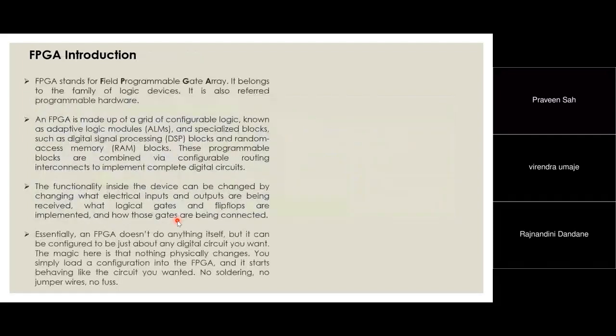With this, if we want to understand the FPGA, FPGA stands for Field Programmable Gate Array. When I say field programmable, it means that after the chip is manufactured by the vendor, you can program or reconfigure this FPGA device anywhere. Whether you are working in the lab, at the customer site, or any place, you can reconfigure it. That is why we call it programmable. With these words, I am a little bit not convinced by field programmable, but reconfigurable, because you can reconfigure the hardware. And gate array, because there is an array of logic gates. That is why we call it a gate array.